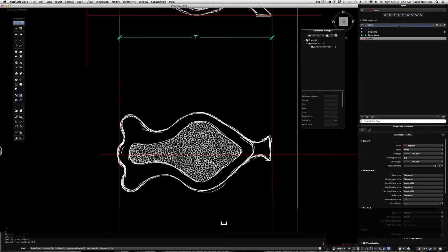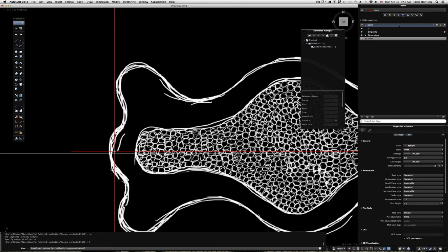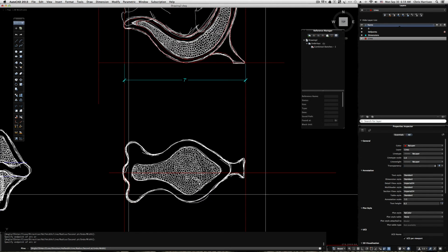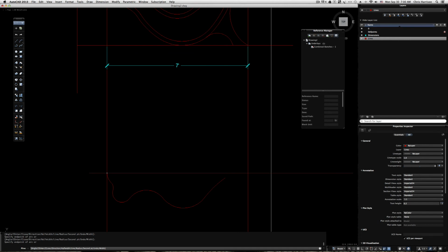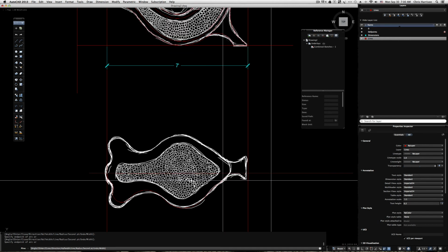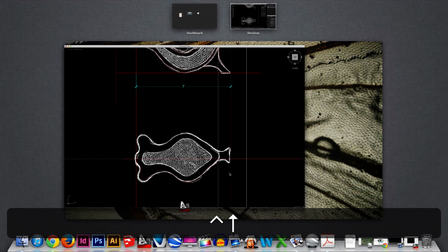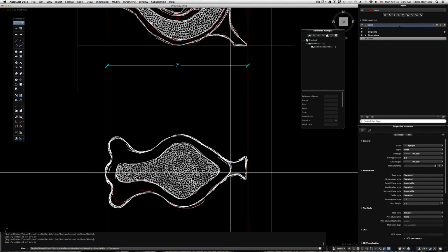I'm going to make just a little bit of a straight line. Well, not even that. Maybe I can just arc this one out actually. Oh, no. Let me make a little bit of a straight line. Okay, and I'm going to hit A to arc out. Okay. And I'll modify my shape a little bit, just to keep that cleaner arc. And to show you all, say it's here, and here, and I will end that. Oh, I hit F3. You need to hit F3 again, but I have to hit function F3, and I'm going to end to this point here.